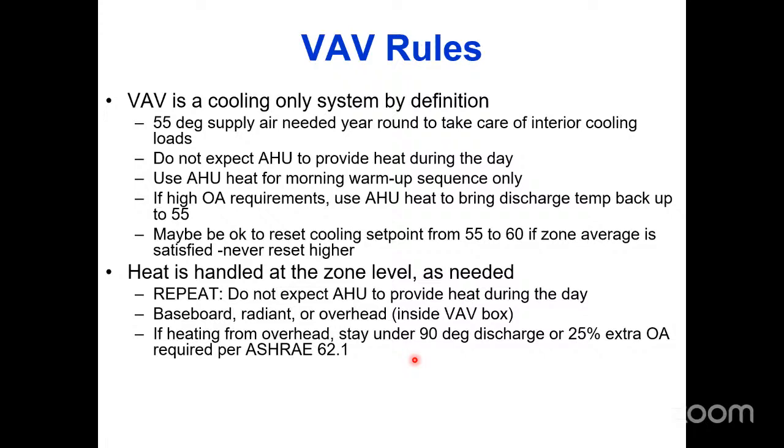I scanned my thermal gun over by the wall and the thermostat said 72, right? And I scanned up the ceiling and it got hotter and hotter. It was like 120-some degrees at the ceiling. It was freaking hot, right? There was hot air coming out of the diffuser. Then I scanned down by the floor where my feet were, and it was like 53 degrees. That's probably why I'm cold. I'm standing on a 53-degree floor and I'm a wuss. So that's the deal. Why is it so hot at the ceiling? Why is the hot air not coming down?